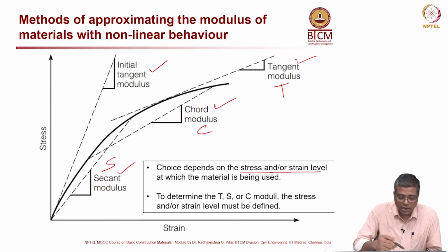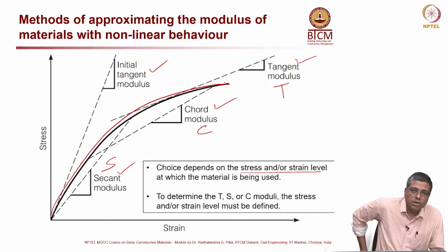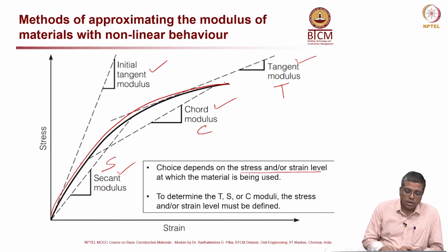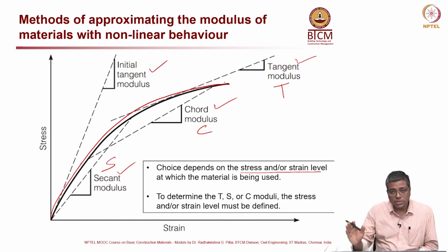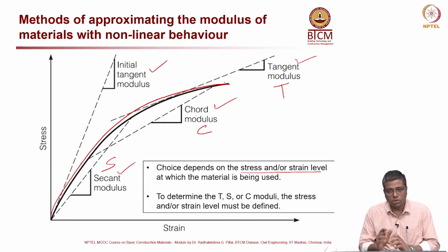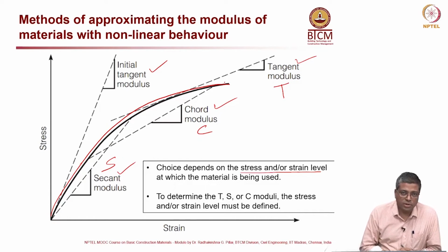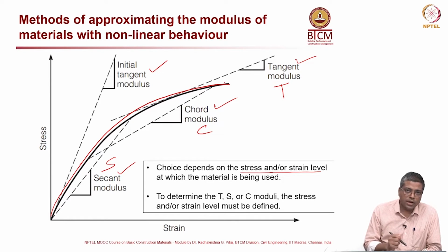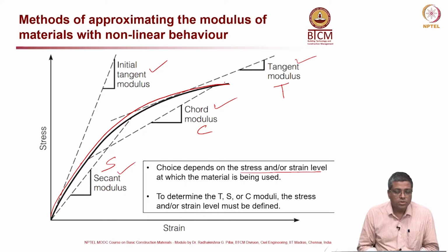So, you can see the stress strain graph here, this thick black line. When you have a stress strain graph of a material, and you know the typical stress level that the material will go through in service, based on the applied loads, I can calculate that in-service stress level, and then use that value and these types of curves from different materials to compare.